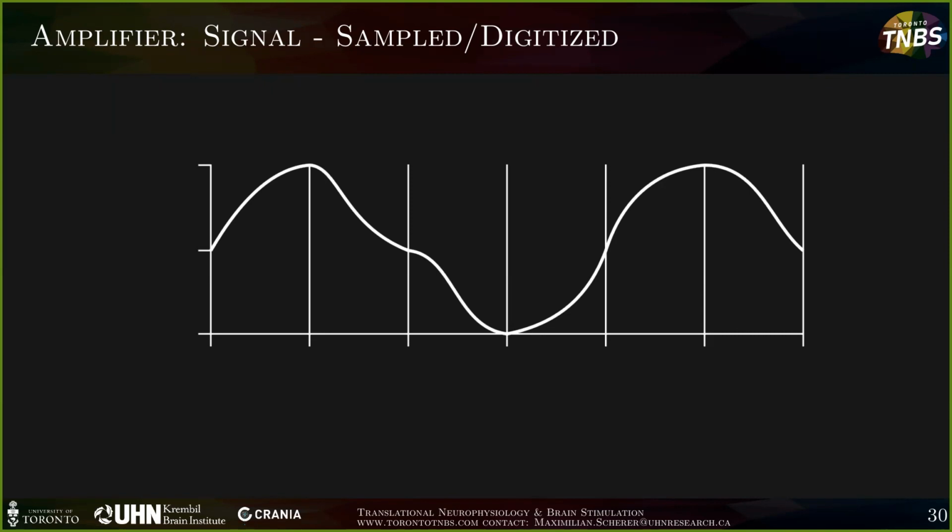But on the other hand, if you have a super high sampling rate, you're going to run into the issue that your amplifier is likely not going to support that, because they are limited in sampling rate, because it becomes really difficult if you go really high. And the other issue is you're going to create super large files that you can neither work with nor store in the end. So you should select the sampling frequency you can work with, and of course the amplifier supports.